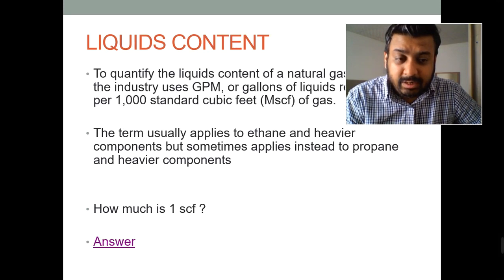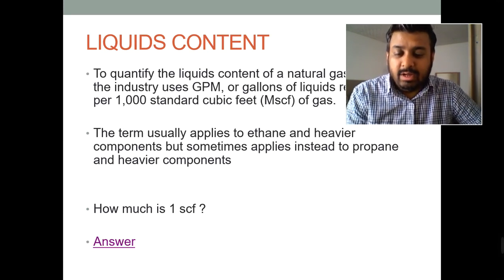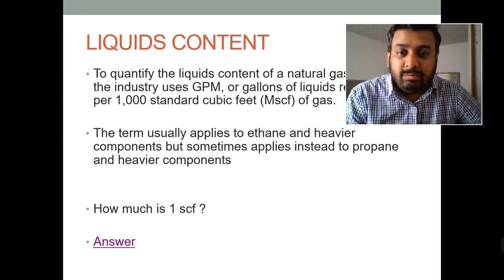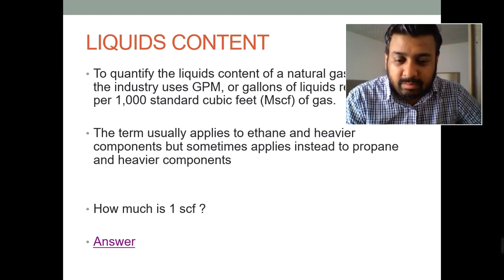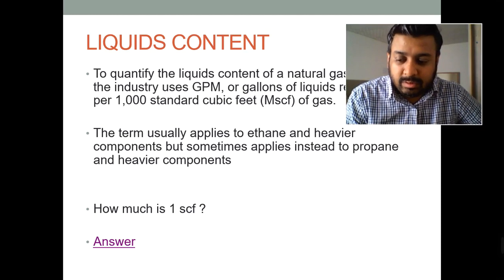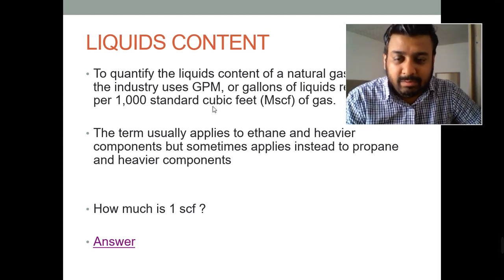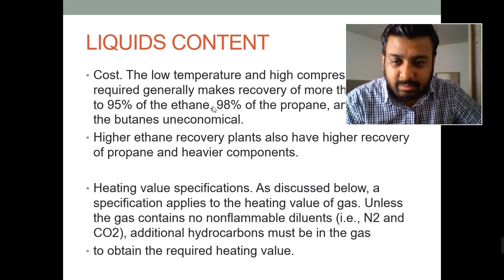Now, it depends totally on economics. It's an economic decision to remove those liquid hydrocarbons from the gas, because if the gas does not have too many hydrocarbons, then what is the point of processing it? Maybe the operating cost is more than the profit you are going to make. So we have to consider the economic cost, the operating cost, and the capital cost. When we have all these costs together, then we can decide whether we can remove the liquids or not.